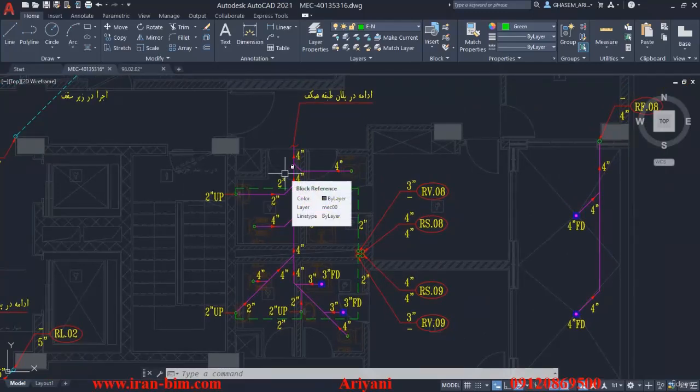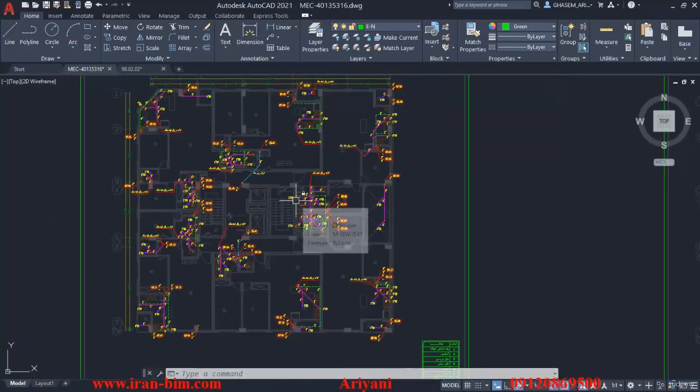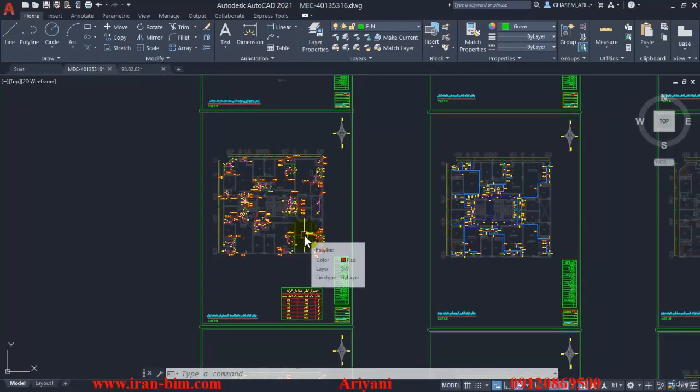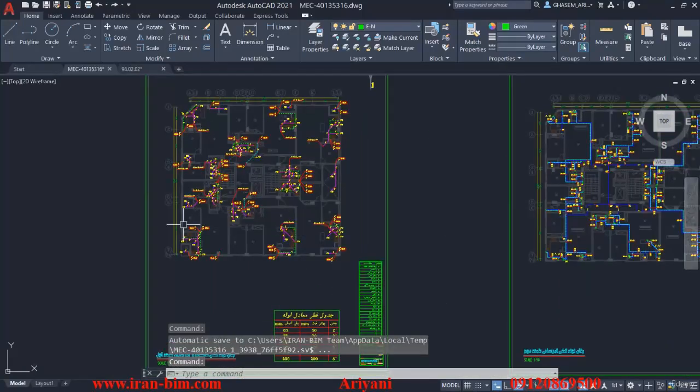So you'll sort out the priority in the BEP for your team or for your contractor, and you'll tell them that we're going to do the work in this order. So now we'll imagine that we've received the planning, and before we get to the modeling, we need to check the plan itself. So there are a couple of ways to go about this checking. The first one of which is doing a simple eye test in which you move around the plan and try to figure it out.